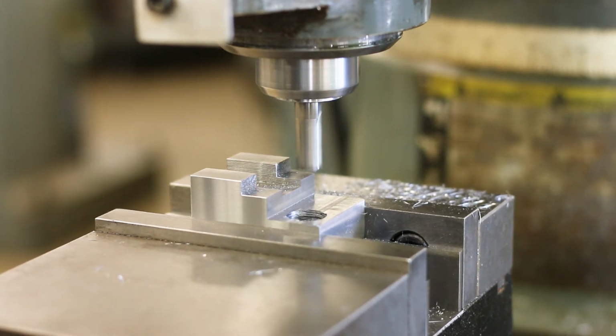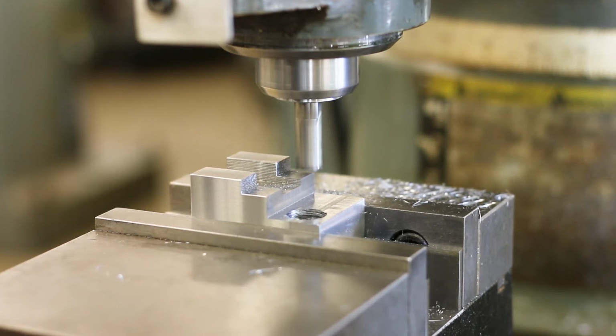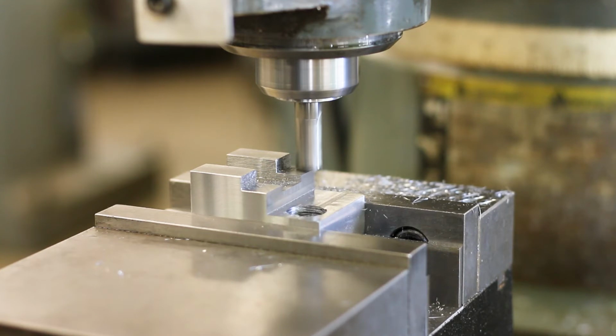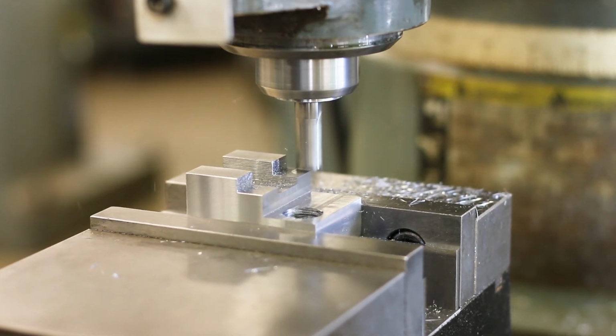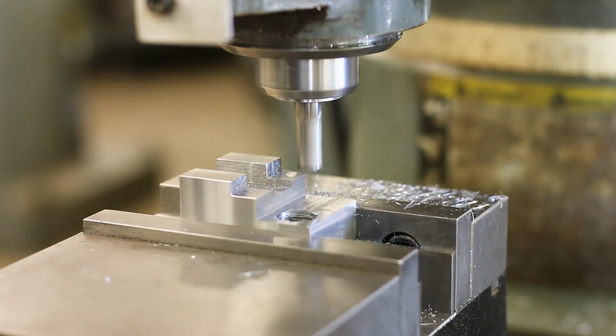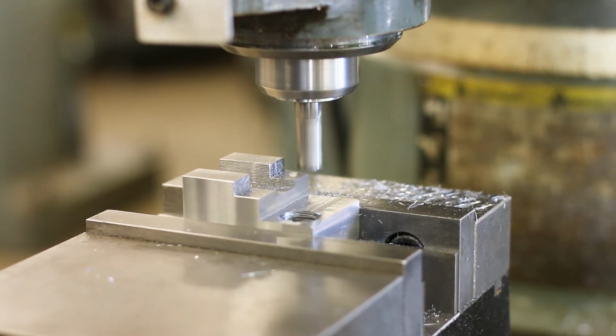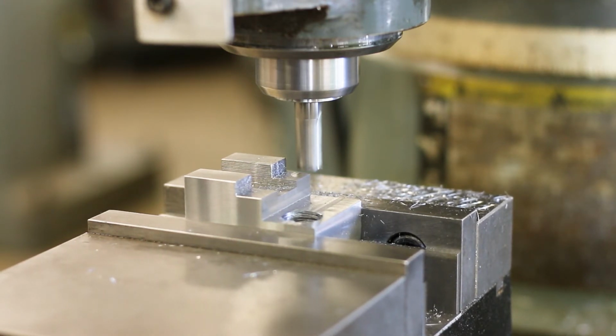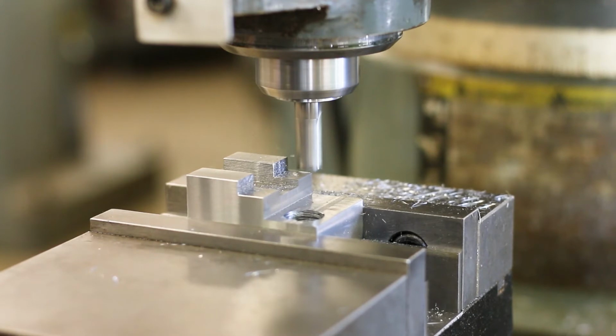Okay, dynamic touch off with the knee, nice and slow. Okay, just touched off there. I'm going to call that 0 on the dial on the knee. Let's go 5 thousandths. Okay, give myself a little bit of material to cut here and then feed across the surface.